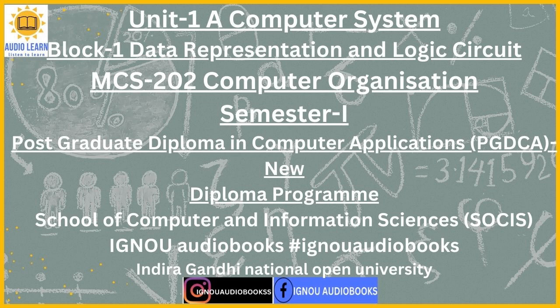Internal data transfer between registers and between the ALU and registers can be done through various organizations, including one or more buses. Dedicated data paths can also be used for data transfer between CPU components on a regular basis. For example, the program counter register, PC, content is transferred to the memory address register, MAR, to fetch new commands at the commencement of each command cycle. Therefore, dedicated data paths from PC to MAR can help speed up this part of command execution.